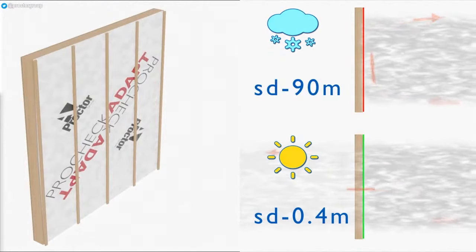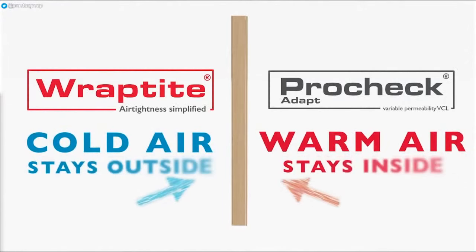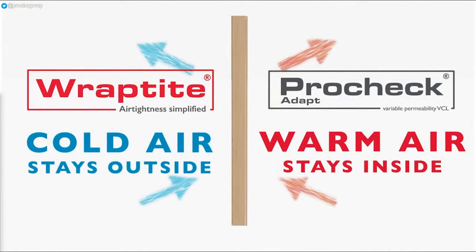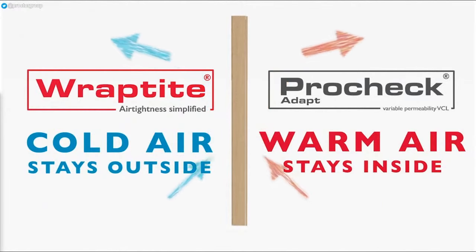ProCheck Adapt's translucent structure eases fixing to structural frames, and in conjunction with the integral tape allows for a fast installation time. Combining the external air performance of the wrap-tight membrane with the flexible internal resistance of the ProCheck Adapt provides a double layer of air resistance to reduce air leakage rates, whilst ensuring an optimum transfer of construction moisture in any direction.